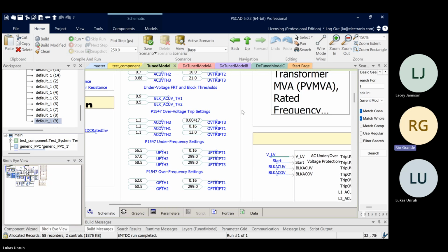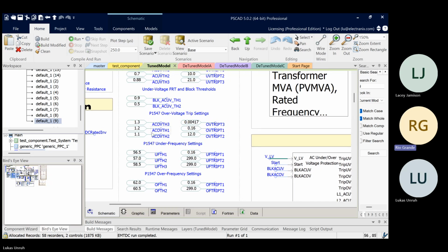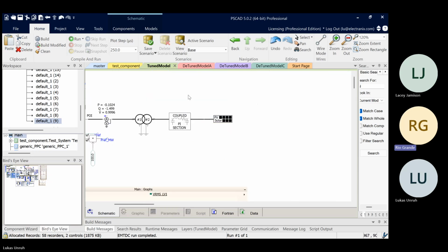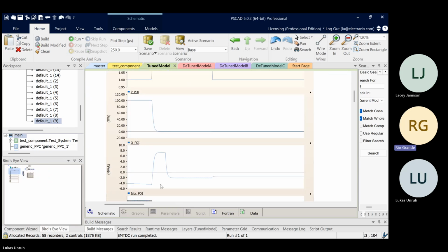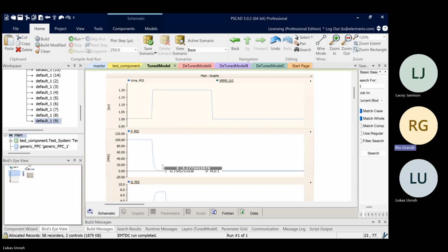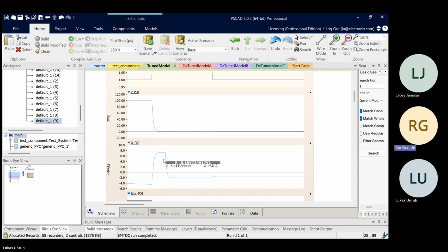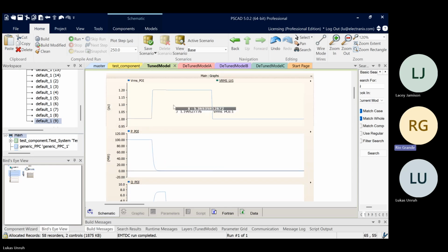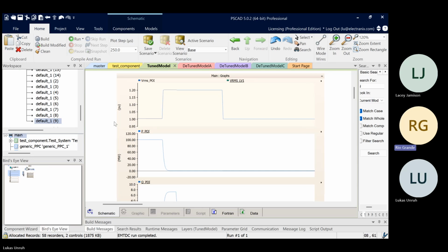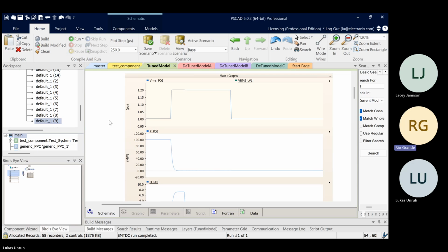In terms of how one fixes this, right? If the plant would be pulling down on reactive, it's actually doing something very strange here. I guess the POI current is going up. That could be just due to the filters on the plant, as we have some capacitors in the filters. So that could be why. But really, we would want the plant to be bucking its reactive power, and so absorbing from the system, and thereby lowering its terminal voltage, and then you could get under that 1.2 threshold, and be able to ride through this test.